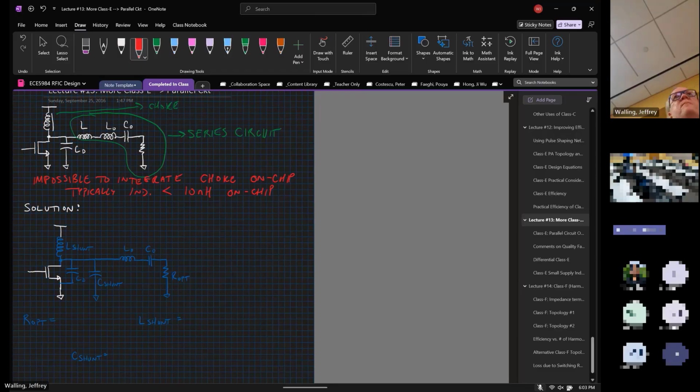Okay, and then what about a linear amplifier, like an LA or something? Same thing, same reasoning. If the impedance looking up into that network is high relative to the signal path, then my signal doesn't want to go towards that thing. It wants to go towards the signal path.